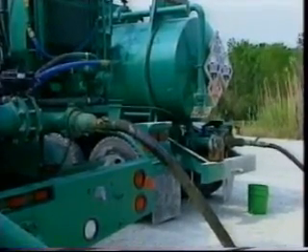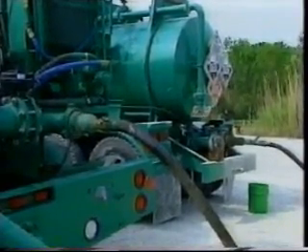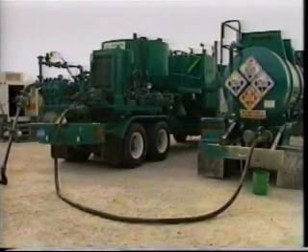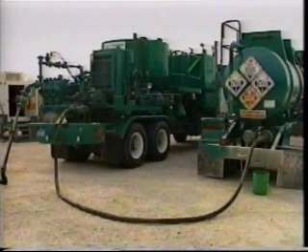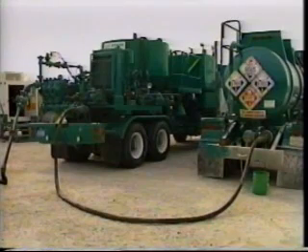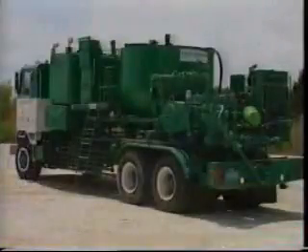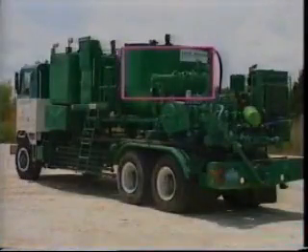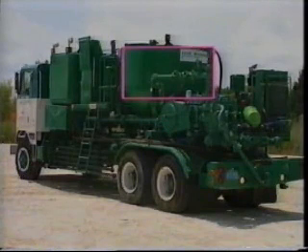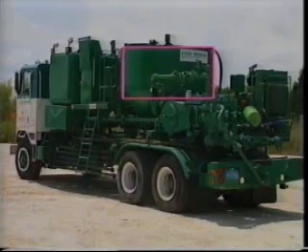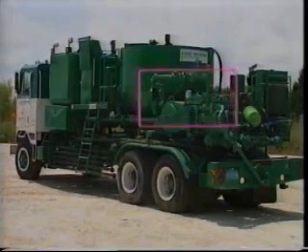Low-pressure lines transfer the treating fluid from the transport to the pump truck. This pump truck is used only for acidizing and gravel packing operations, never for cementing. Such exclusive use eliminates concerns about contamination from other fluids and cement. Two open 10-barrel tanks located at the front of the pump truck are used to measure the load water. The 25-barrel mixing tank at the rear of the truck is provided for situations where the mixing of gelled fluids is required. It will not be used on this job.